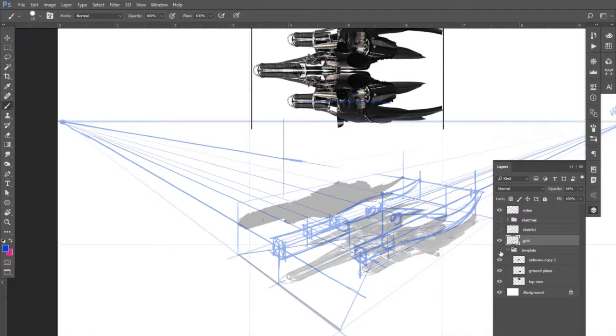So I'm going to turn off the template for just a second, take a look. Okay. If I draw a line from the center of my cylinder up here to that top center peak, that should really help me set up the center mass for my piece. So I'm actually going to go down to my sketch tool and do the same thing. I'm going to go from here to here. Oops. Let's go back to pink with X. Right, center mass.